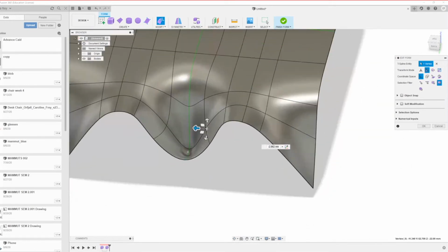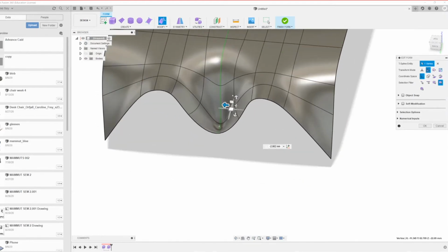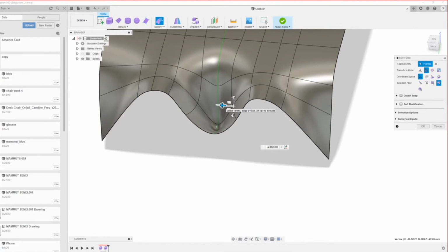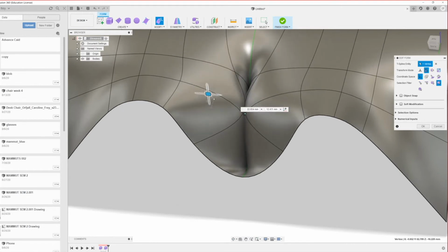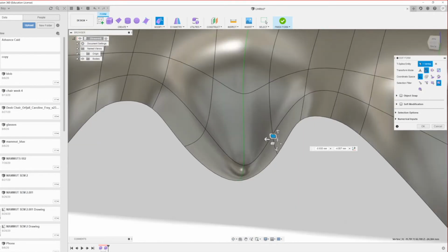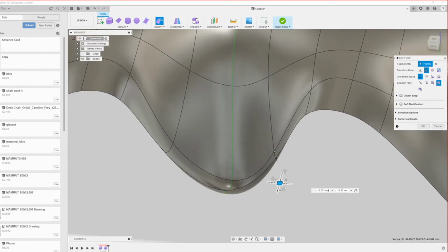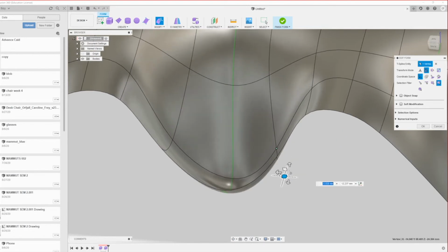Because as you are going along, when you're editing those forms and using this, we call it in Rhino the gumball, it also shows the different maneuvers that you can do with it. So you can make those things a lot narrower. For example, if I brought this in as I did before, that would make that area narrower. And if I brought in the other one, it would probably bring it down more or up, or we can even go more in like that.